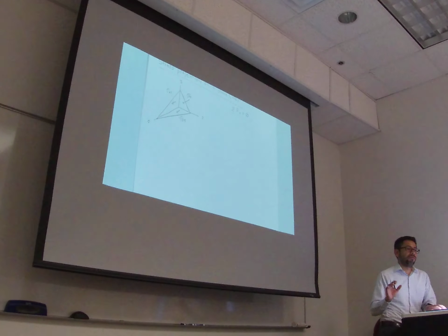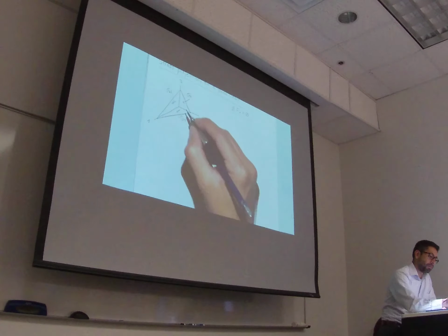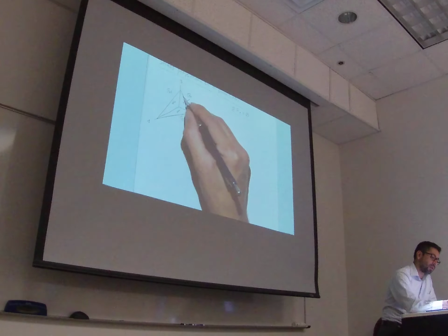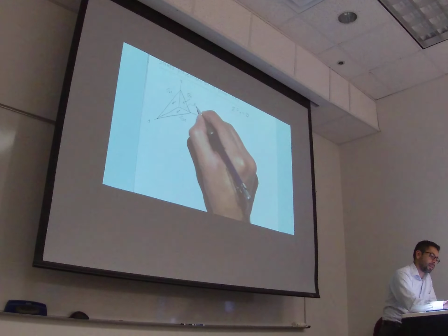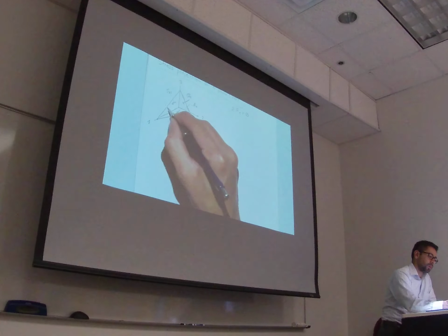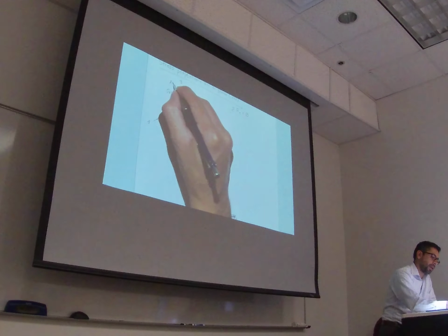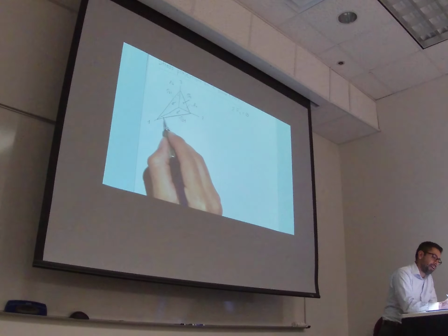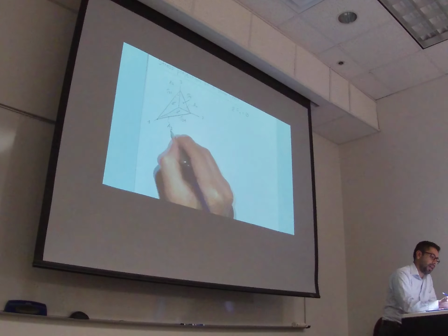Well, these are stresses. These are not forces. So if I want to make the equilibrium, I need to multiply them times their respective areas. So for example, this face over here is going to have an area A1. Face number 2 is going to have an area A2. And face number 3 is going to have an area A3.